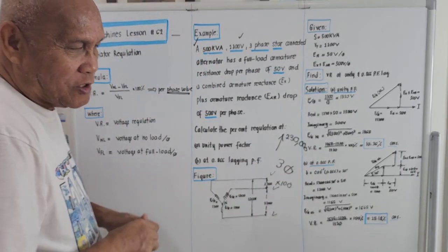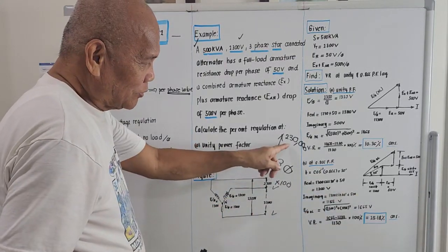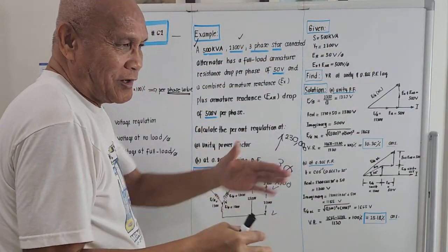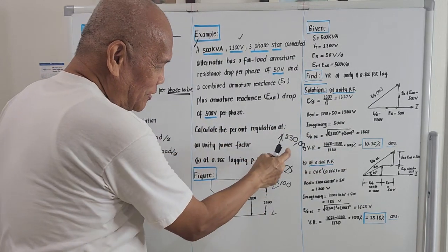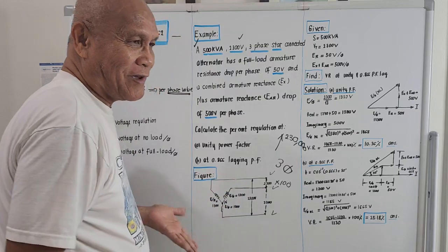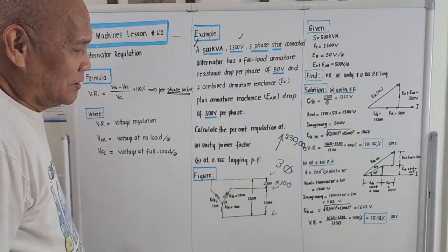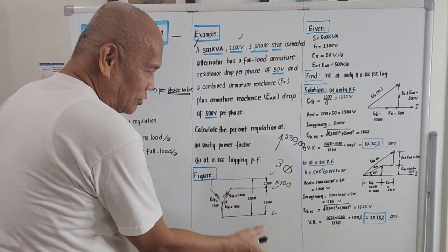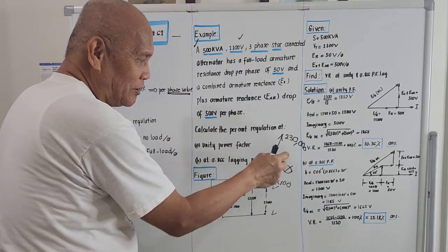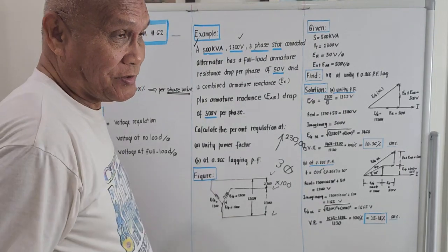If we transfer this energy over a long distance at a voltage of 2300, it would hardly reach the end of the line. If the voltage is small and the delivery distance is too much, your light will be gone before it reaches your house. So from the alternator we step up the voltage to a certain value, and that's why transmission lines for the primary are very dangerous. That's high voltage.